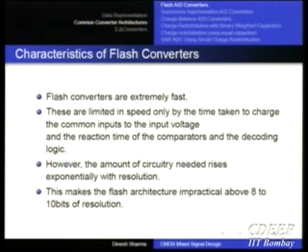And the complexity essentially rises exponentially with resolution, and about 8 to 10 bits of resolution is the most that you can perhaps think about. Even that, 10 bits is 1000 comparators in parallel across the input, is not an easy job to do. So beyond that, it's certainly not practical.